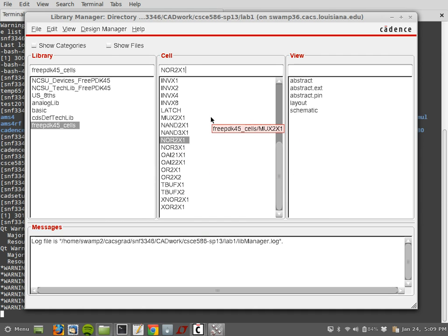This is a very, very limited library. It's an educational research library. If I show you a commercial library, for each gate it has 30 cells maybe. There's like 2 input, 3 input, 4 input. And for each of these, it has multiple transistor widths. So this is a very small library compared to actual commercial libraries. But it's enough for our purpose here.